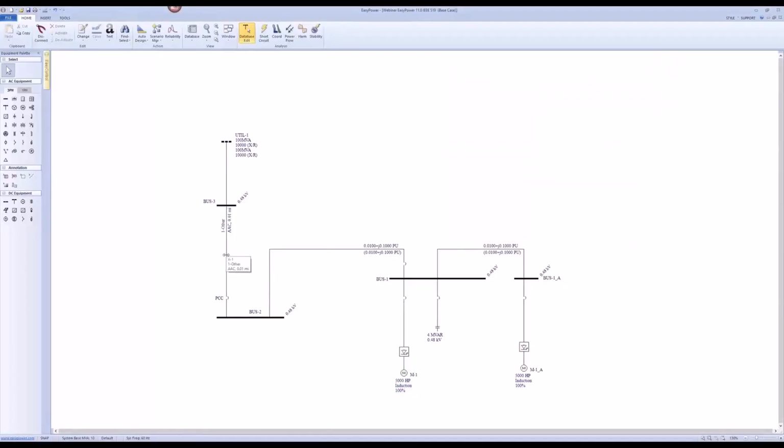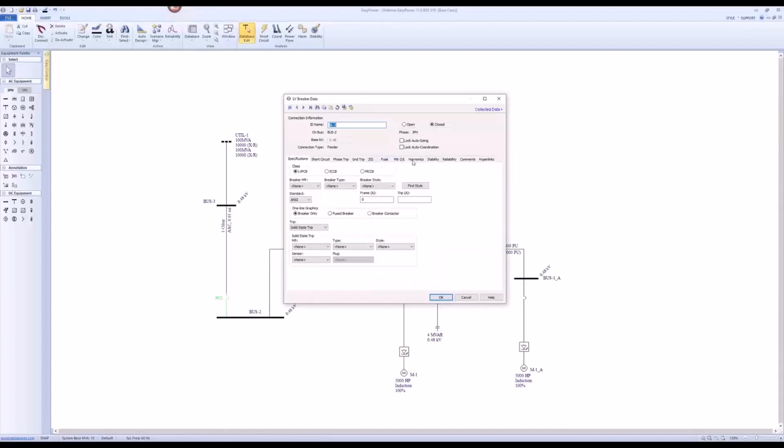And another branch, which is a transmission line to connect my site to the utility system. Of course, I define my point of common coupling breaker at the point of interconnection here, right? So if I put my PCC, I know that I have to model it as a 519 point of common coupling. How do I get my kVA demand? How do I get my ISC versus I load?